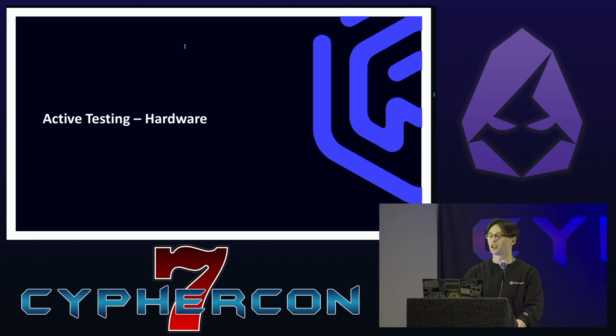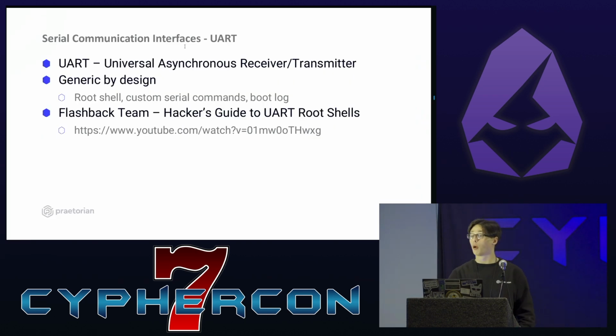So you have to know what's kind of in scope here. One thing you're going to encounter a lot is these serial UART interfaces. UART is Universal Asynchronous Receiver Transmitter. As you might be able to determine from the universal, these do not have one sole purpose. Sometimes you'll connect to a UART interface and you'll get a root shell.